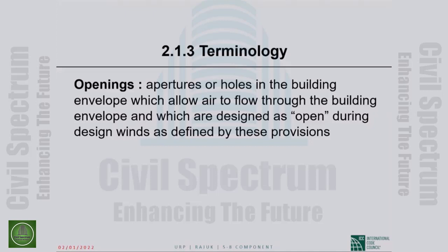So an opening, let's take a door or a window. Is it an operable door or a window? Is it an opening or is it an enclosure? So this is saying that an operable window is an opening if it is going to remain open in the design wind event.